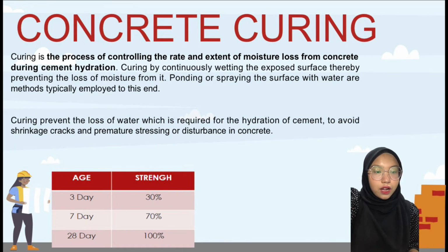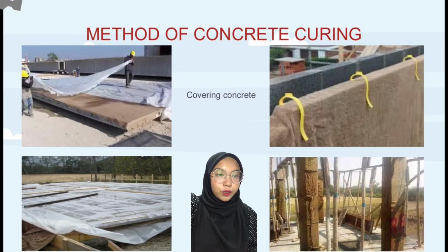I will show how we want to test the curing strength. If the curing is 3 days, it will be 30%. If the curing is 7 days, it will be 70%, and the curing 28 days, it will be 100% and more strength.